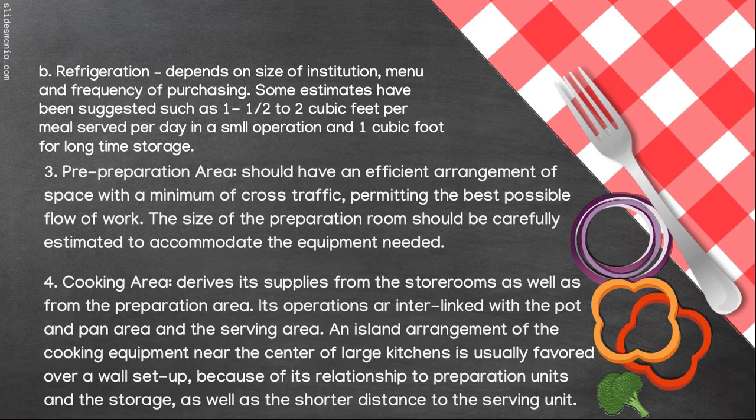And then refrigeration depends on size of institution, menu, and frequency of purchase. Some estimates have been suggested, such as 1 to 1.5 to 2 cubic feet per meal served per day in a small operation, and 1 cubic foot for long time storage.